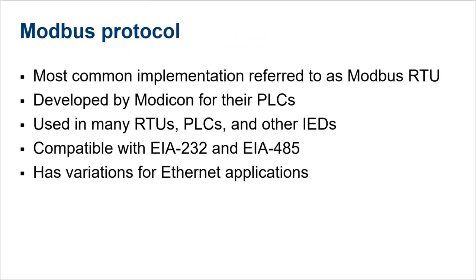Modbus protocol is a much simpler option. It's one of the most common protocols that you'll see. The most common implementation is referred to as Modbus RTU. This is the pure serial form of Modbus. It was originally developed by Modicon for their PLCs, but these days it's used in many RTUs, PLCs, and other IEDs. It's compatible with EIA 232 and EIA 485 in all their different forms, and there are even variations for native Ethernet applications.